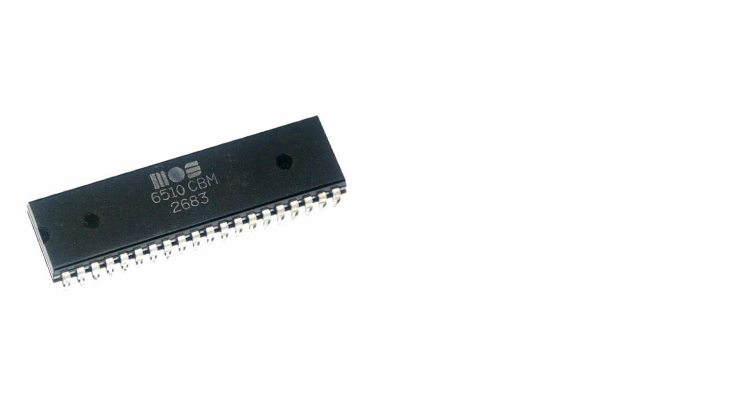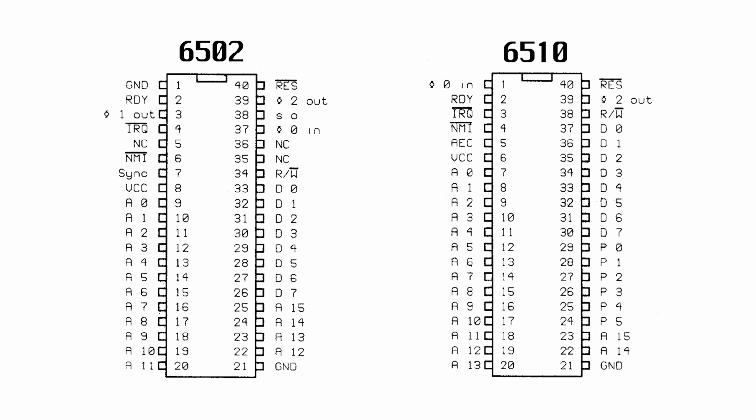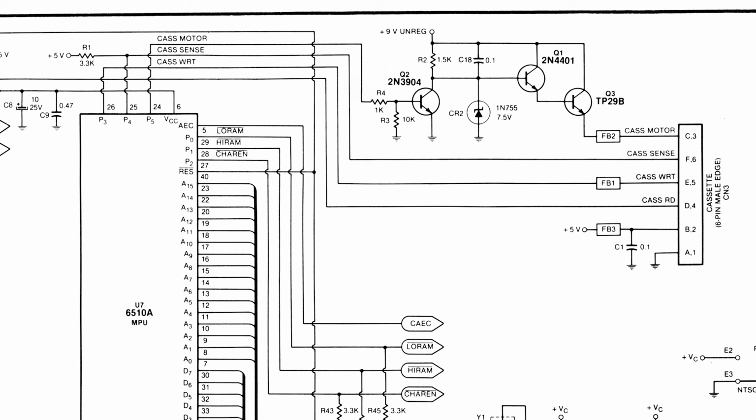The 6510 is the CPU on the Commodore 64. A lot of people just think of it as a 6502, and it's mostly true, except for a key difference that we care about here. The 6510 added a 6-bit processor port. These are 6 physical pins on the 6510 that are wired from the CPU to different chips. That way, the CPU can use those signals on those lines to talk to different chips and not waste any addressing space on I/O addresses.